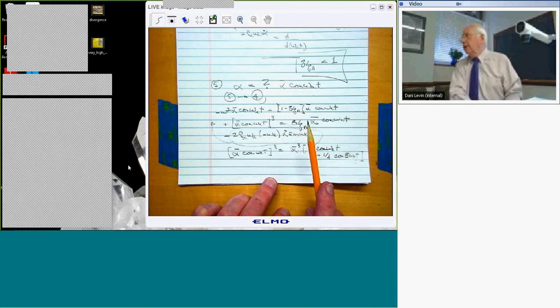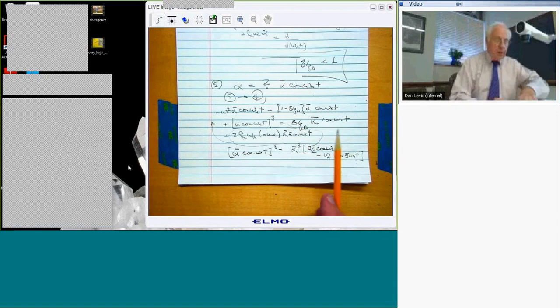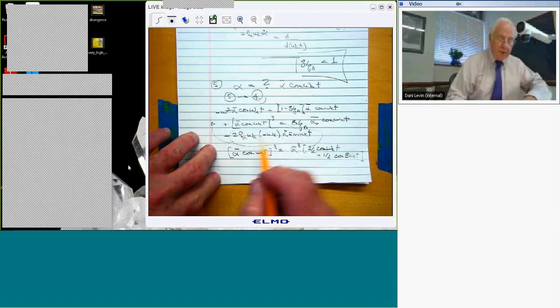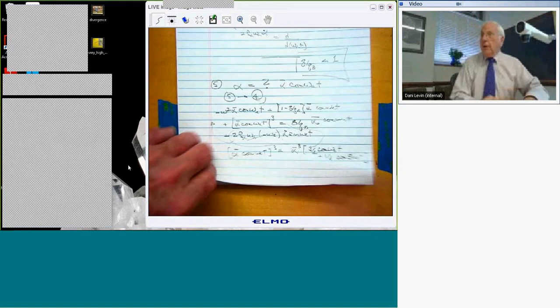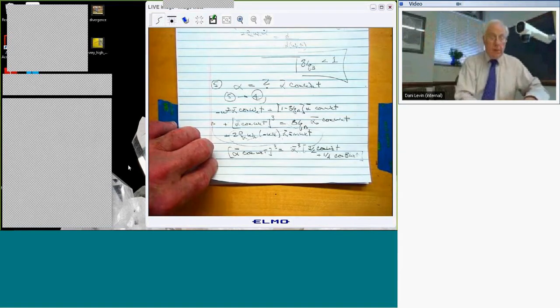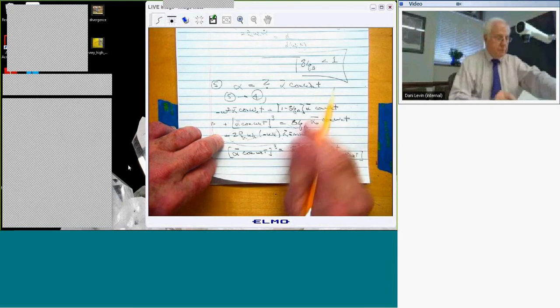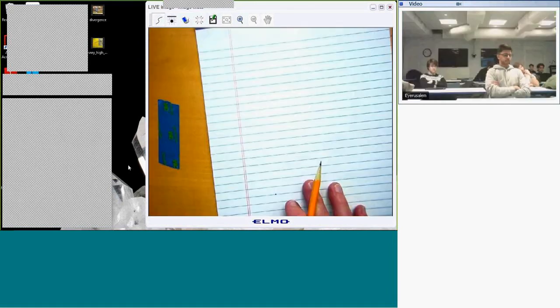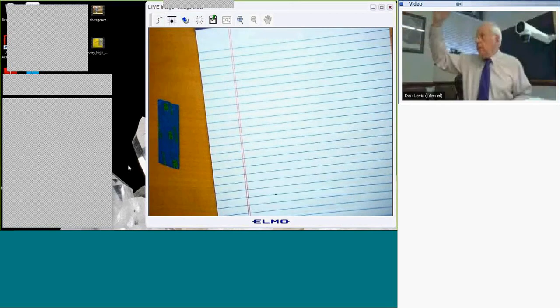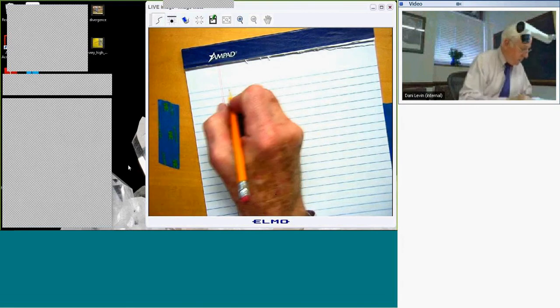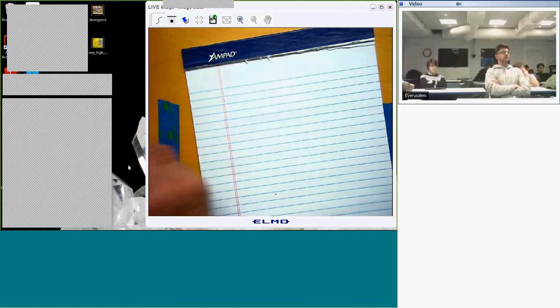Right? Okay. So I'm now going to ignore the damping term and balance all the harmonics, just the first harmonic, though, because that's all I can do given what I have seen. Okay, so now canceling out all the cosine omega e t that appear in each one of those, I end up with the following. Let's call this equation 6.